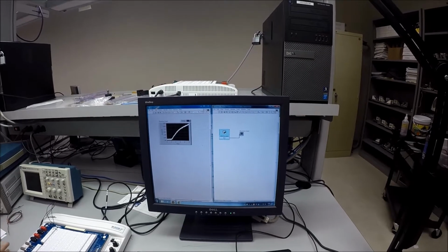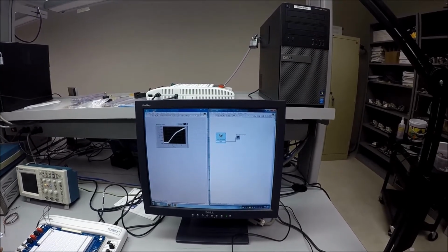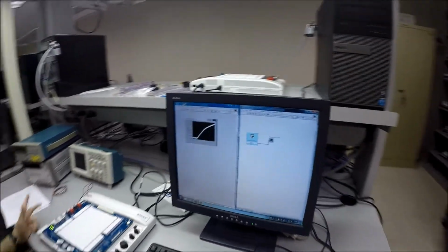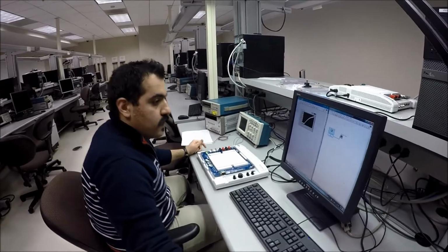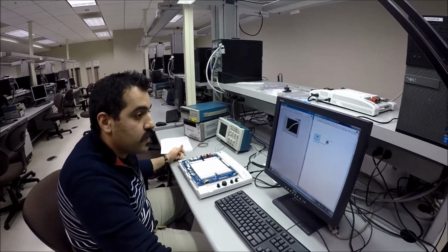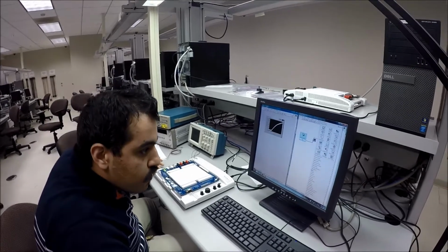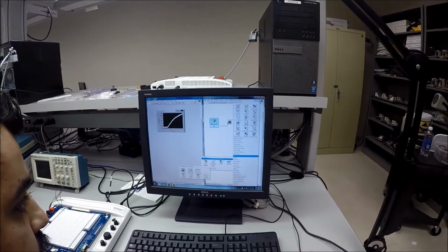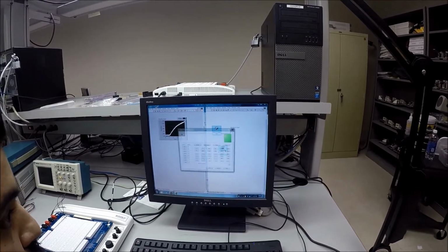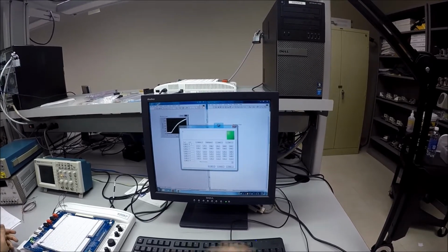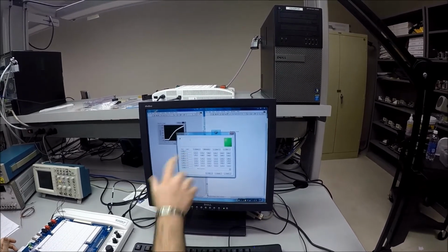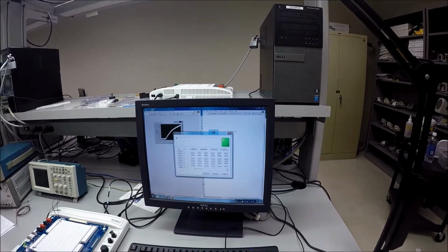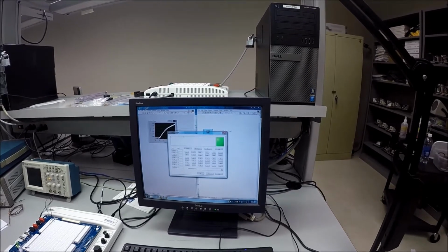Now we want to model the temperature as a linear function of voltage. To do so, we need 2 pairs of data, temperature and voltage. So just for the sake of argument, let's go with room temperature and body temperature. We go to the Express menu, arithmetic and comparison, and bring a formula box in order to make that formula. Our variable is voltage V. We change the label to V, and we now have to make our formula. I made it with just 2 numbers, as I said, room temperature and body temperature.